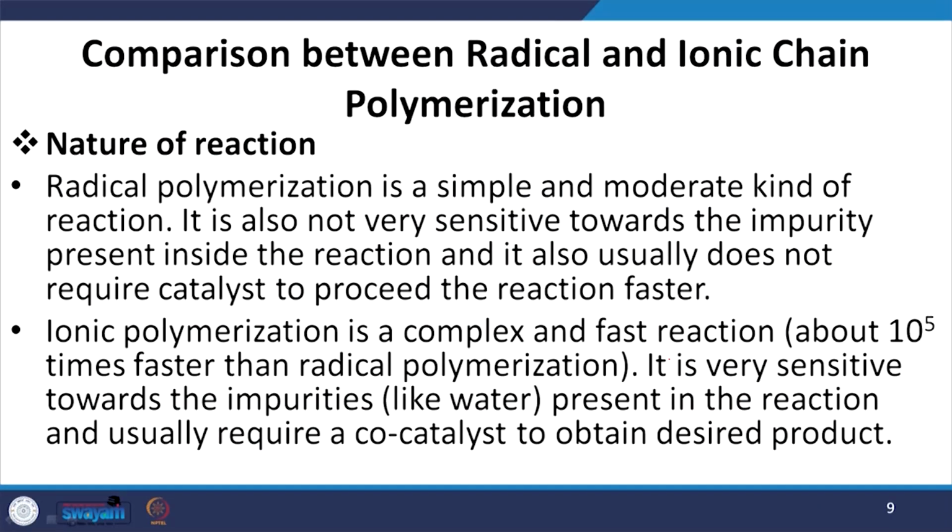Another important factor is the nature of the reaction. Radical polymerization is a simple and moderate kind of reaction. It is also not very sensitive towards the various impurities associated with the reaction mass or reactants, etc. And it usually does not require any kind of catalyst to make the reaction proceed faster. So, these are the things related to radical polymerization.